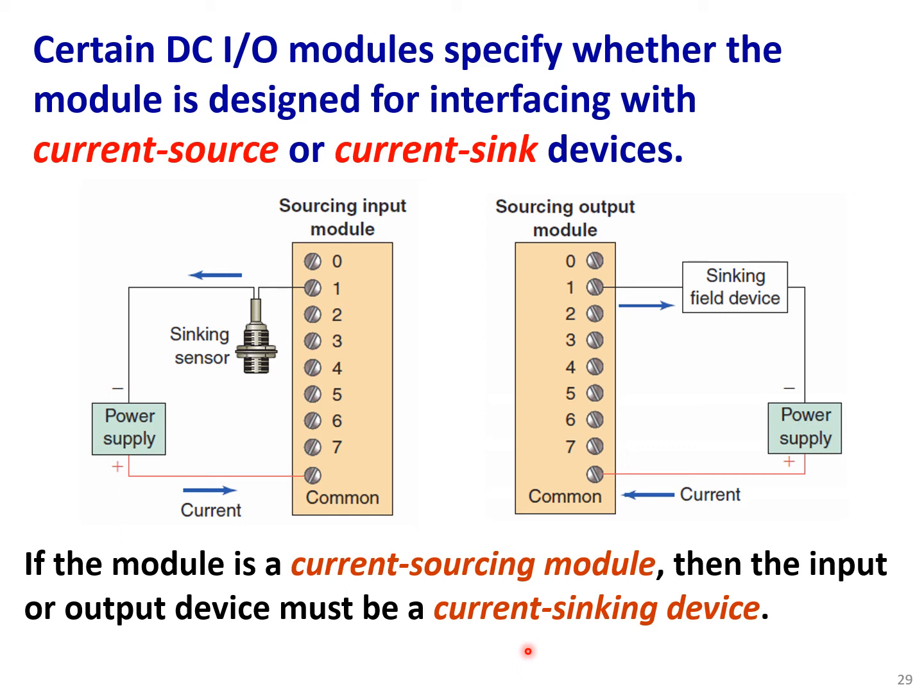Okay, so here we have our sourcing input and sourcing output, and the field devices, let's say this sensor, is sinking current.